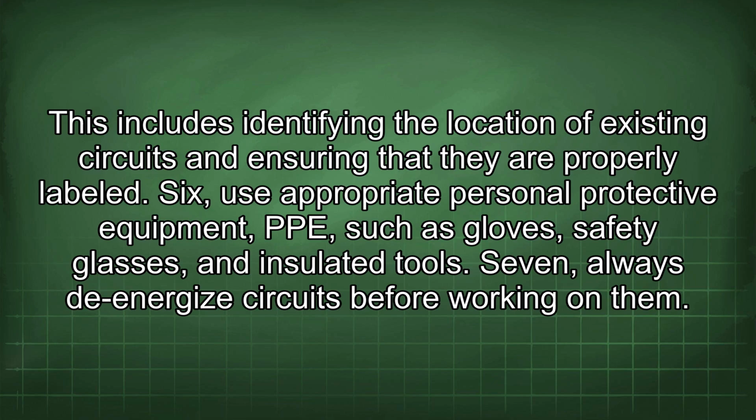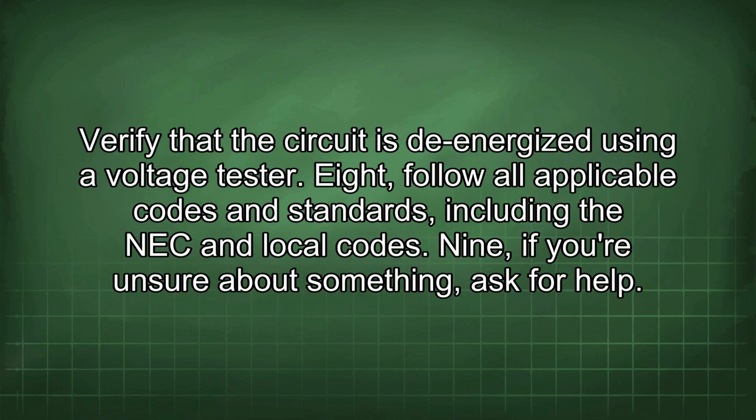6. Use appropriate personal protective equipment, PPE, such as gloves, safety glasses, and insulated tools. 7. Always de-energize circuits before working on them. Verify that the circuit is de-energized using a voltage tester. 8. Follow all applicable codes and standards, including the NEC and local codes.